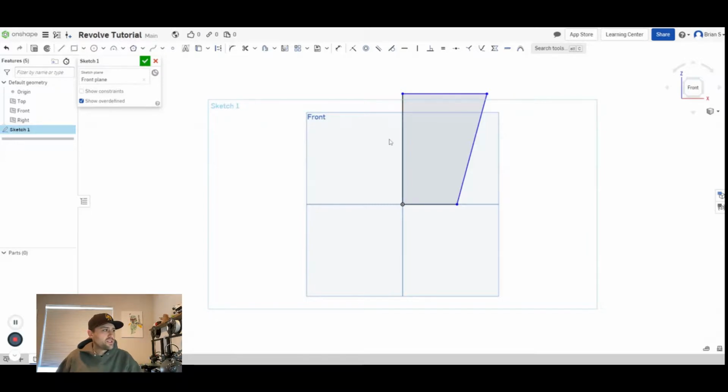But of course we need to put dimensions in as well. And I am going to put in a construction line center axis there, and I'll show you why in just one second. So click on the dimension and the bottom of the cup. Now if I dimension from the point to the center line and then I move my cursor to the opposite side of the center line, it dimensions to a diameter, which is of course much easier to measure and to specify when you are measuring or defining a circular object. So I'll click there, and that is 2.2 inches.